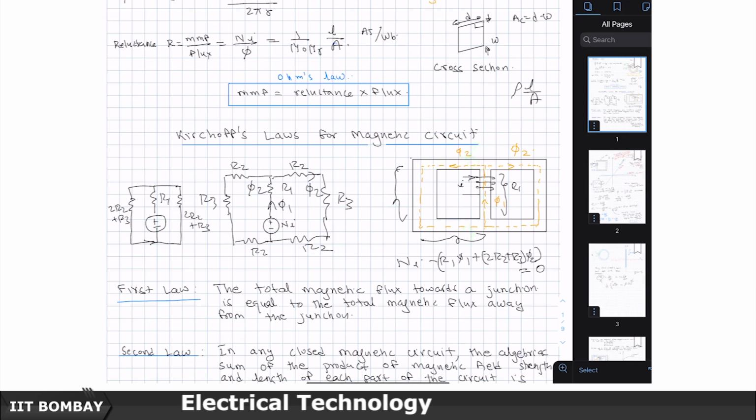The use of this geometry is that basically the flux which is being set up here, I am able to break it into two parts, usually equal parts, and bring it back in this direction, in this way. So, if the flux set up here is phi, then because the flux lines cannot accumulate, they have to keep flowing.